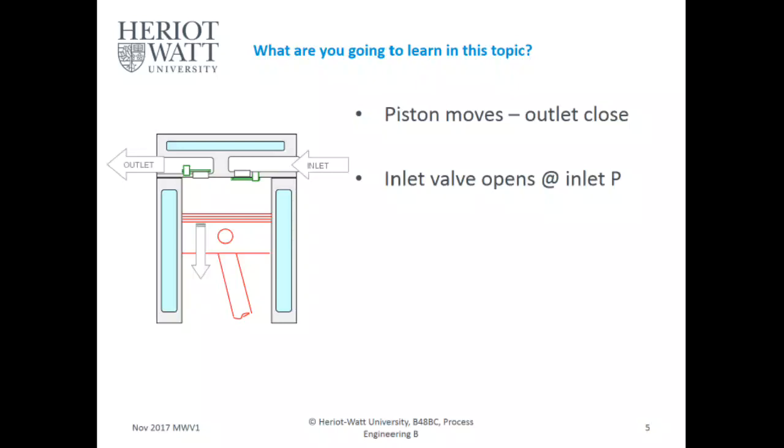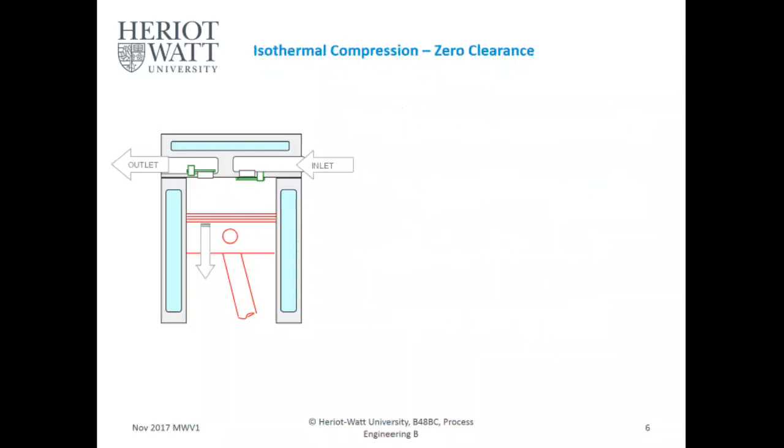So you get the gas at pressure 1, let's say 1 bar. It pushes it up to, let's say, 3 bar, and it opens up the outlet valve, and that's basically your compression cycle in the reciprocating compressor. So the reciprocating piston continuously moves up. It's like an engine, basically. So the piston closes, the outlet valve at outlet pressure opens and pumps your gas out.